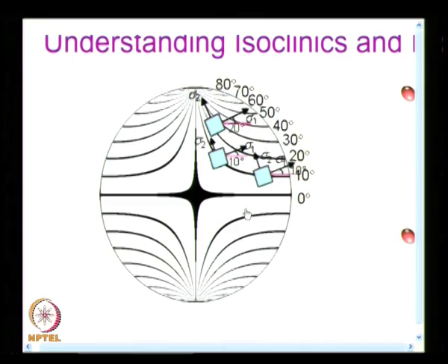That is why people asked, can I plot the isoclinic field for every point in the model domain, and digital photoelasticity has now achieved that. You may have to take a few images and process the intensity, and it is possible to generate plots of this nature by post processing the data acquired. In a conventional polariscope, I have to keep it at 0 degrees, 10 degrees, 20 degrees, 30 degrees, and for each of them carefully draw the isoclinic sketch. And there is also something very interesting.